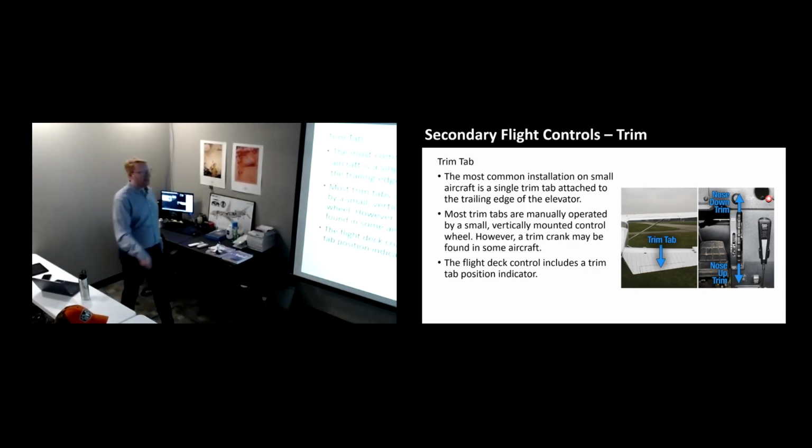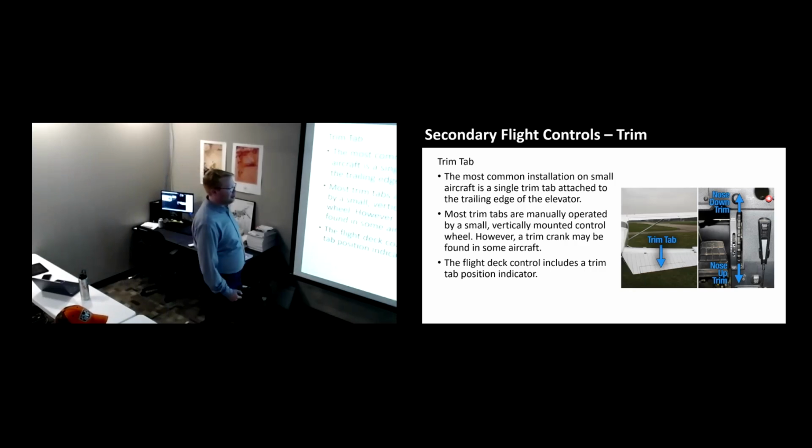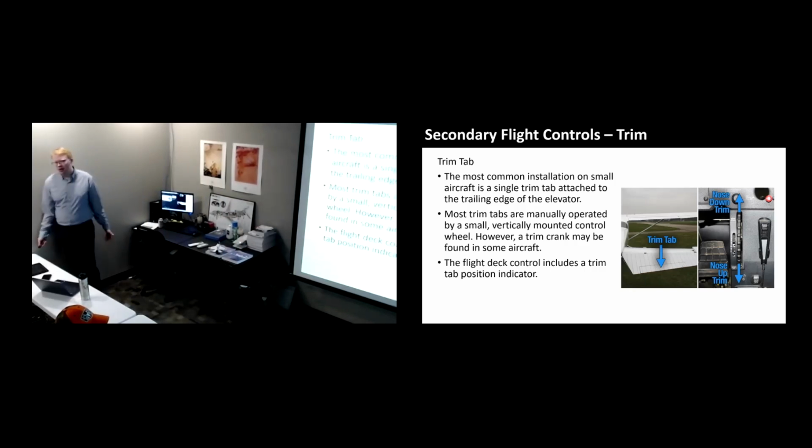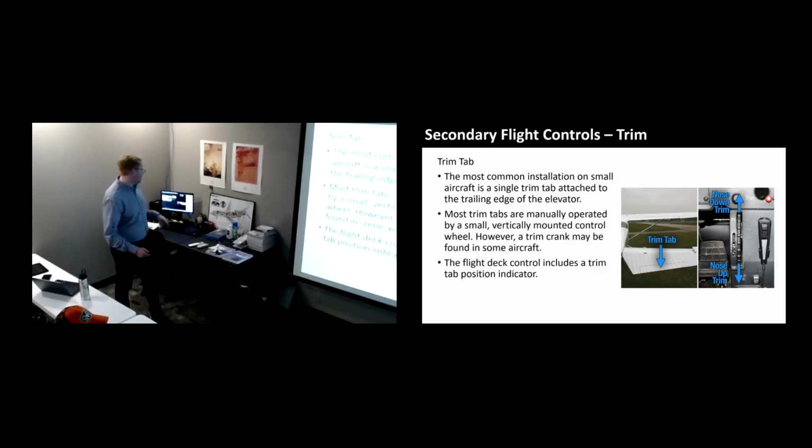As you move that trim piece nose down, it'll adjust this trim here to allow the surface to give you a nose down force. As you trim the other direction, it gives you a nose up force. Now, exactly how they all move is going to take a little bit more mental thinking here, but